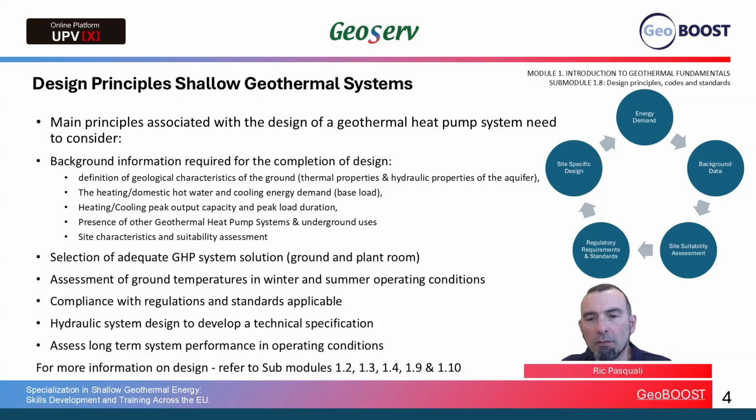So in order to comply with those regulatory standards and requirements, generally a geothermal system designer needs to consider the ground temperatures in winter and summer operating conditions. They need to ensure that the hydraulic design of the system from a technical standpoint works correctly into the manufacturer's specifications and the long-term performance of the system, and in particular the ground temperatures and the performance of those with respect to the operation of the heat pump are met throughout the life cycle of the system.